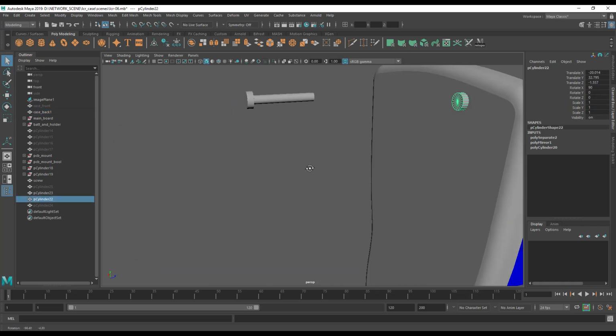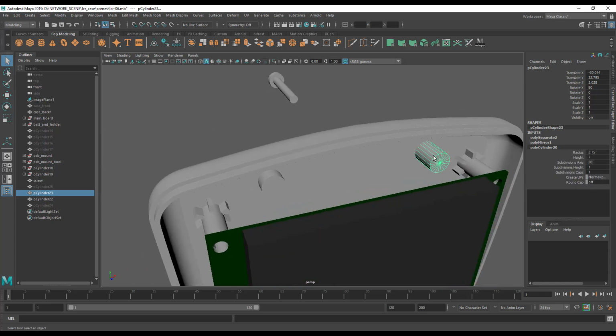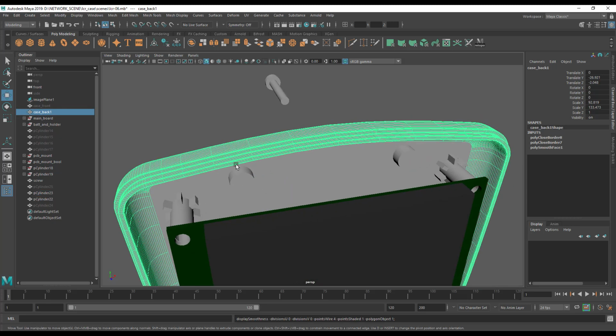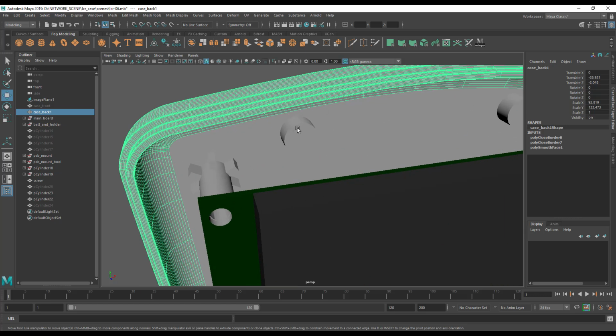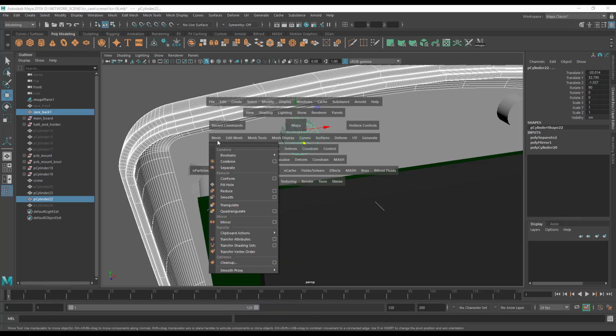We've now got our nubs through here. These should be our 5.5mm holes. Let's just verify that. 2.75 they are. Let's bisect this one also. Okay, and let's cut the holes. So now we don't need to smooth, because this is the unsmoothed view now. So I won't have the same issue. So I'm going to select this, Mesh, Boolean.